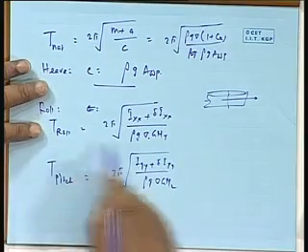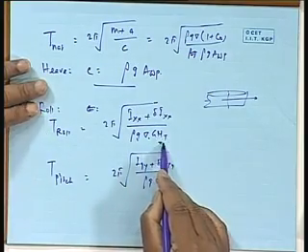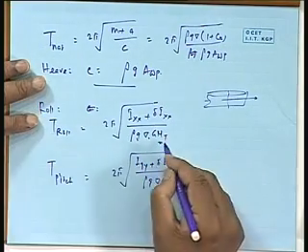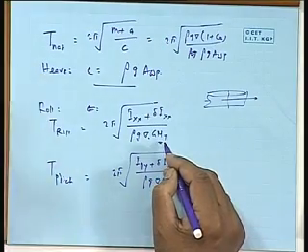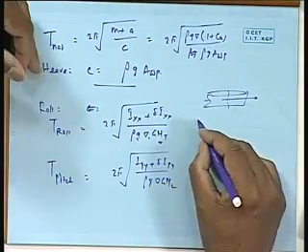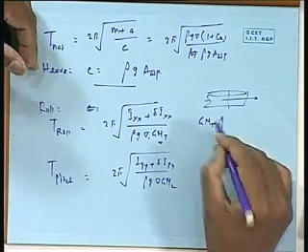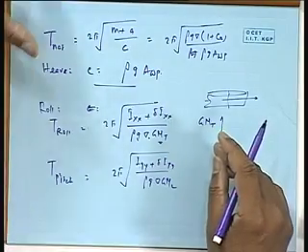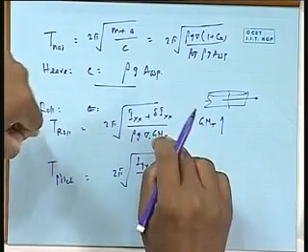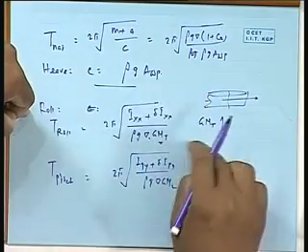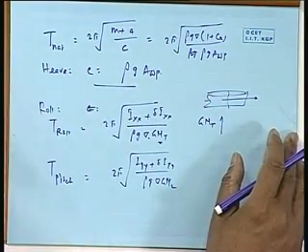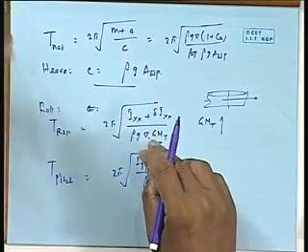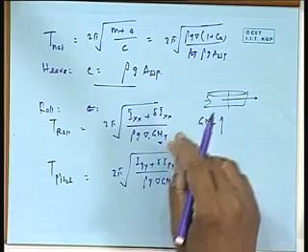In here you see T roll. It is inversely proportional to GMT. If GMT is low, T roll will be high. If I have a very stable ship, GMT is high. You want GMT to be high for high hydrostatic stability. GM high means very stable. But if GM is high, then T roll becomes low. For a very small ship with high GMT it may be 8 to 10 seconds, but for a bigger ship maybe 12 to 14 seconds.